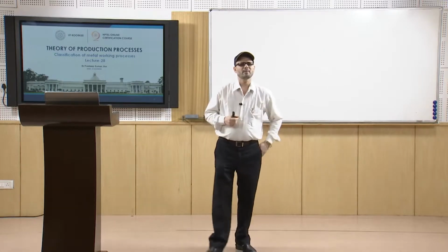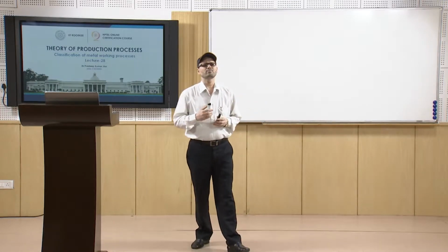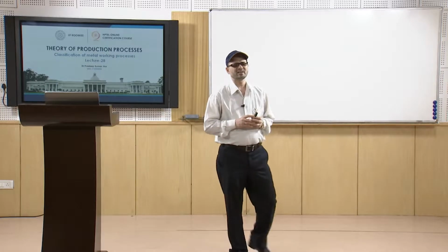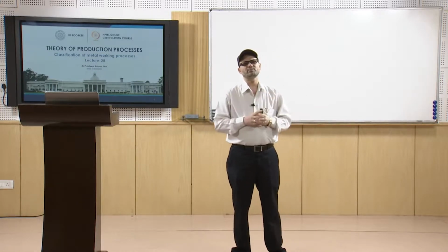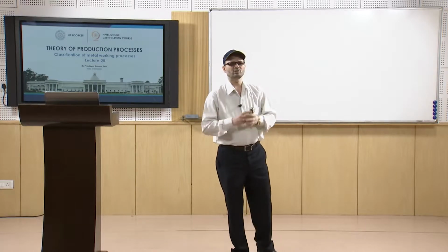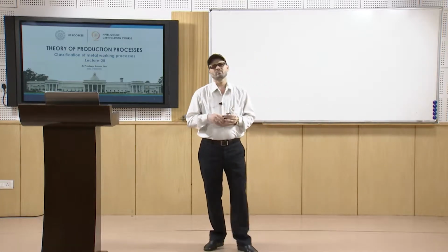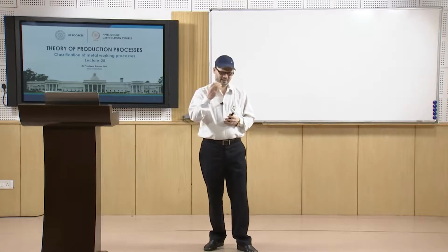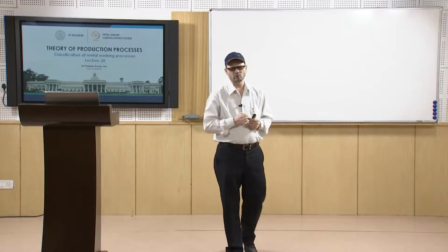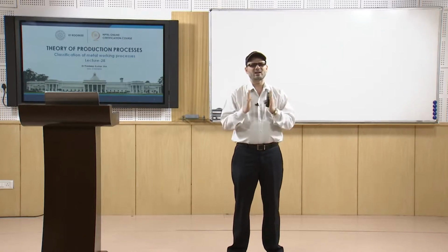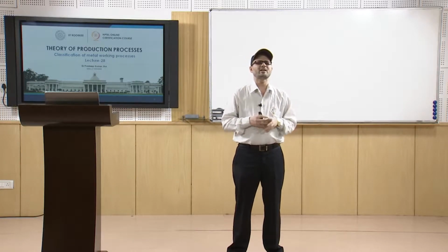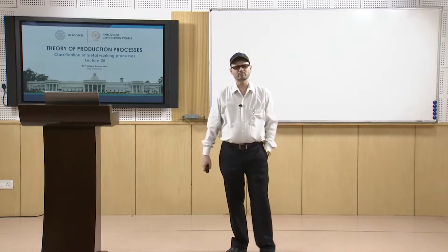This way you have improved properties. In many cases your impurities are gone, especially the shrinkage defects, gaseous defects, blowholes or the air inclusions which are inside are welded. So, these types of properties are improved.